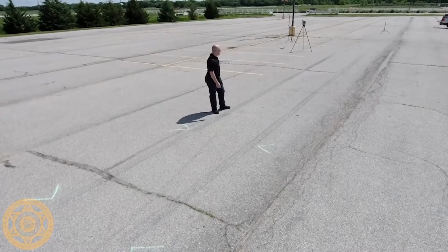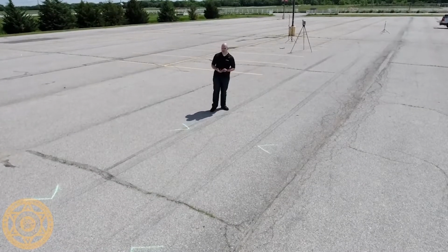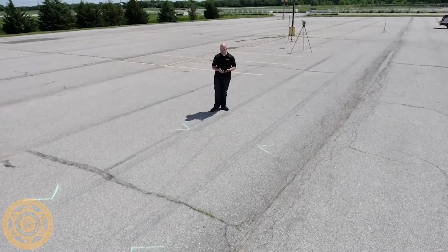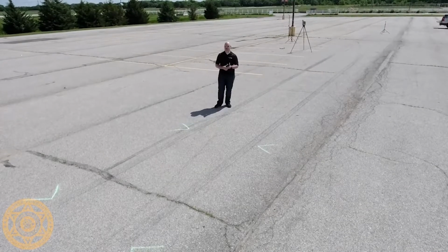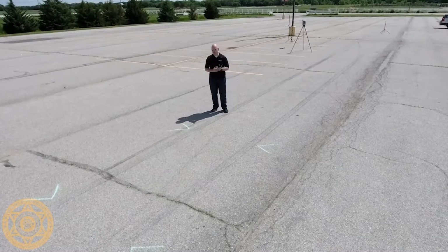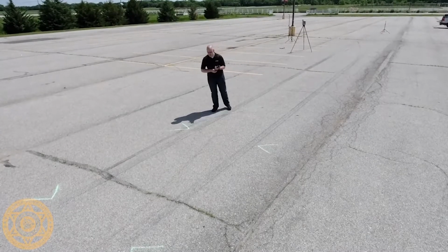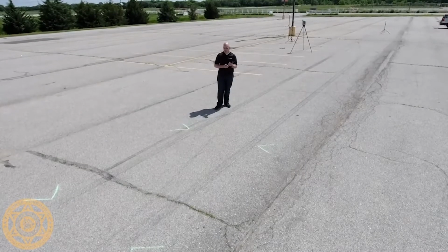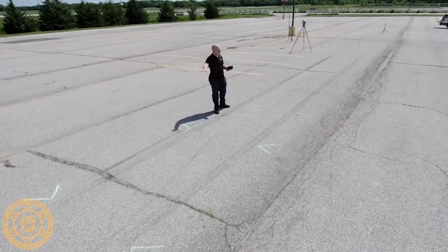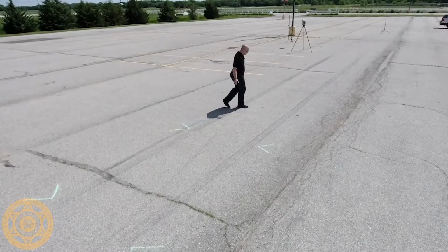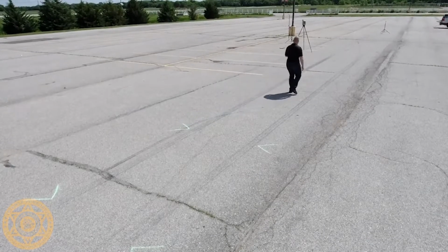At the end of the broadcast today, there is going to be a little bit of a contest to determine how fast I was going. You're going to have to be within 3 miles an hour of my speed here. With that, the friction that we're going to use for this roadway is a 0.80 for these skids on the roadway. Okay, so we have 4-wheel lock skid marks coming out here, and they come to our scanner. So I'm going to walk back here.